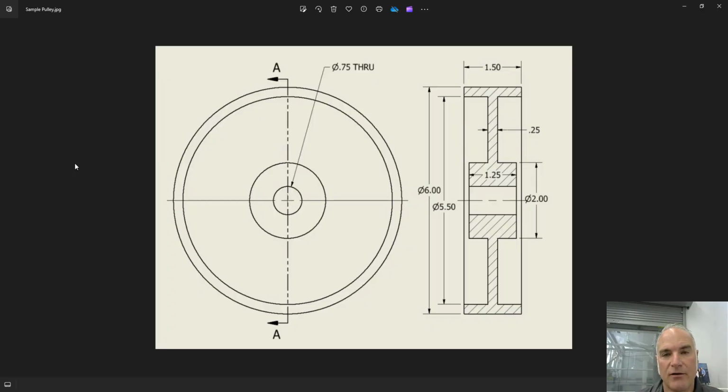One of the strengths of Autodesk Inventor is the ability to capture design intent even in the sketches that you create. In this video, we're going to show how to create a sketch that shows linear diameters so that when you create a revolution and then later on the drawing, as I have shown here, you can simply bring those linear diameters out of the sketch and into the drawing. Notice that I've got a front view here, which is the circular view. I also have a side view shown in section, which we will be demonstrating later on in this course. To begin with, we will want to start our sketch on the side view as shown here.